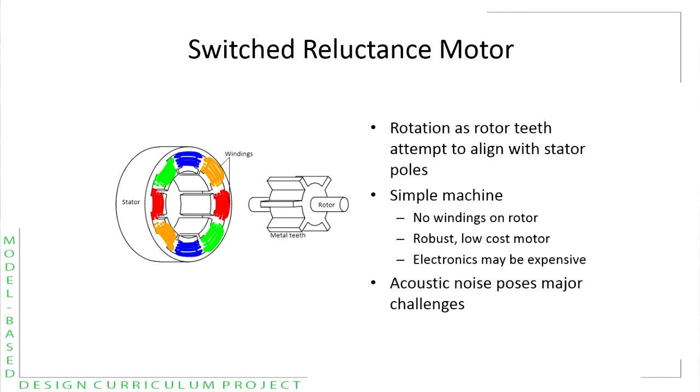The reluctance in the magnetic field is analogous to the resistance of an electric circuit. In order to maintain the rotation, an electronic control system switches voltage on the winding of successive stator poles in the sequence such that the magnetic field of the stator leads the rotor pole, pulling it forward. The motor has the disadvantage of significant torque ripple that appears as cogging, resulting from the difference between maximum and minimum torque with the rotor rotation. This also produces acoustic noise that further contributes to its limited use. However, promising research is being conducted to minimize this deficiency.